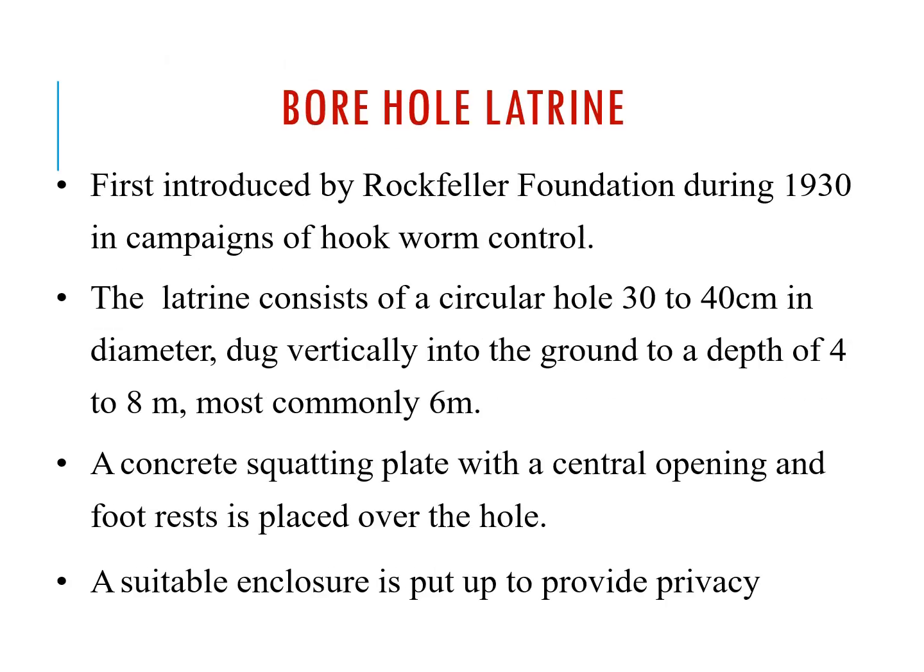What do you mean by a borehole latrine? It was introduced by the Rockefeller Foundation in 1930 to campaign for hookworm control. At that time, hookworm was a very big issue. It was a high magnitude problem. So a latrine was constructed to prevent the transmission of worm diseases, which are usually soil transmitted.